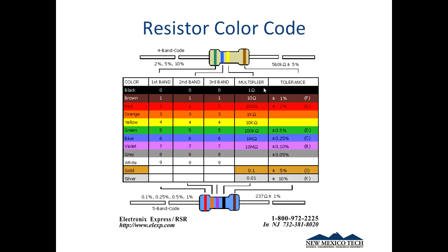And you'll notice they're all powers of 10 here. So it's basically whatever you get times 10 to the whatever color here. This is convention. This way you can put little tiny colors on resistors and know what value they are without having to write in a number and have somebody read it on little tiny resistors. I will caution you though, about just using the resistor color code.